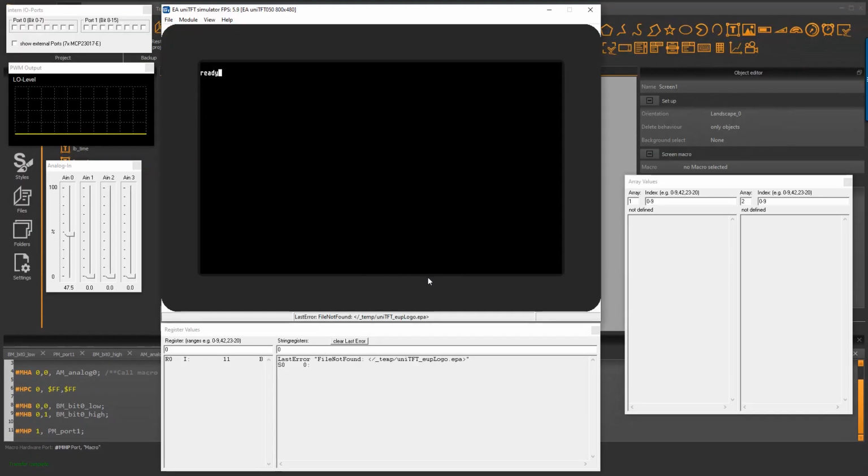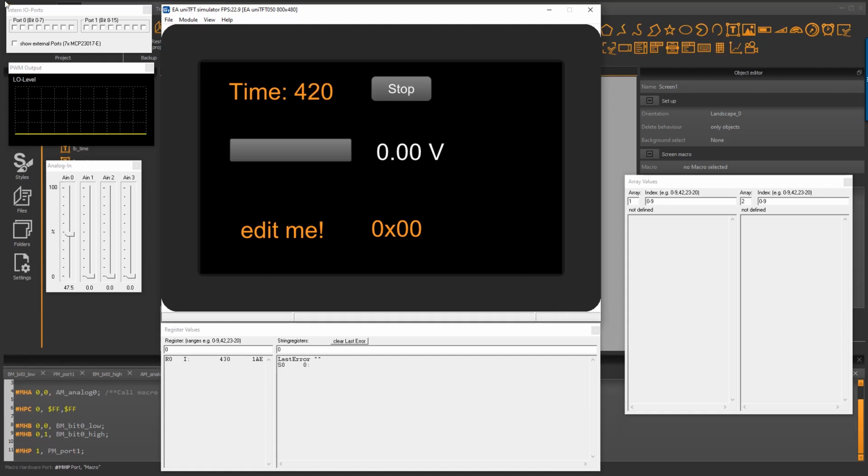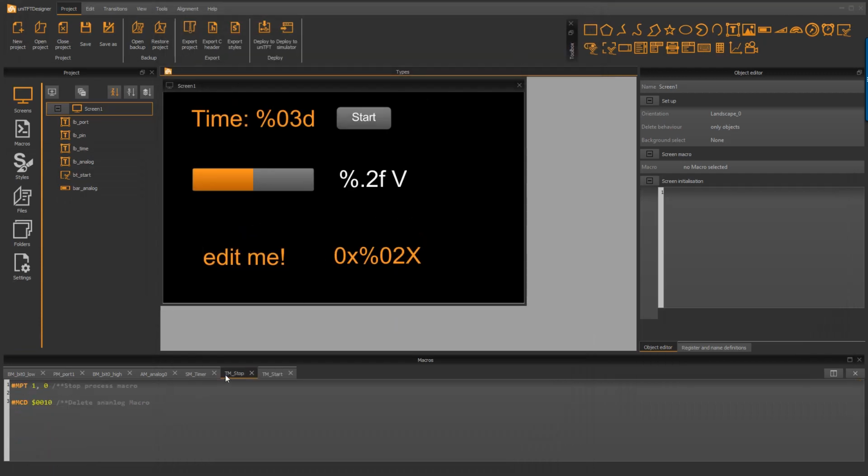I start the simulator with F6. I press the button Start so the I/O macros are active. I change bit 0, the label alters between high and low. Changing the other pins, nothing happens, till I change one on port 1. To complete the sample, we need to add the clearing definition in our stop macro. Only the 2 bits 4 and 8 must be ORed.